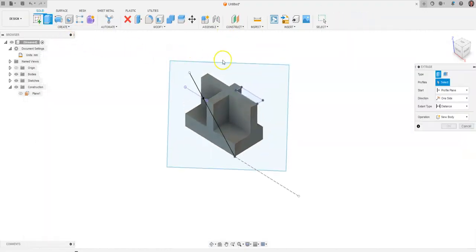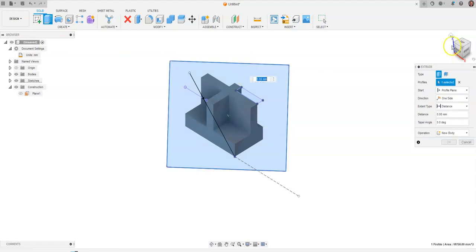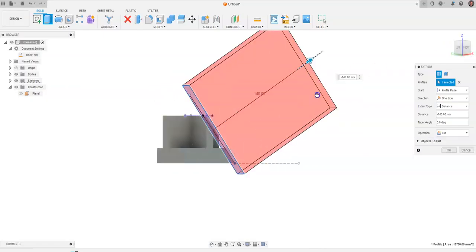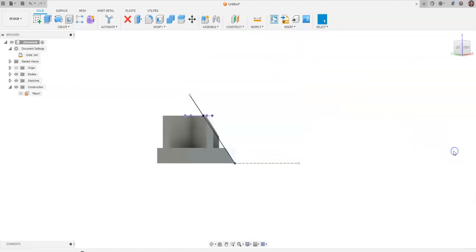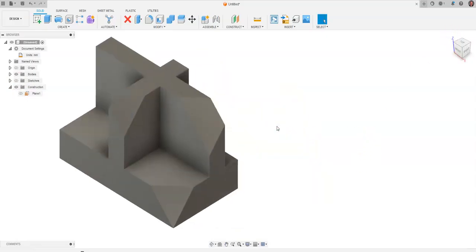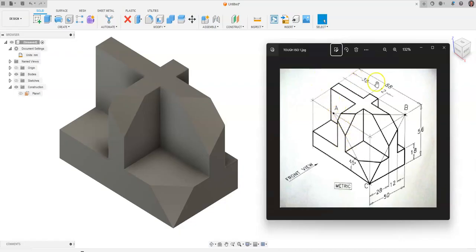We're going to grab Extrude, and I'm going to tap inside of that object, and we can even go to the side here, maybe a little bit of a different view. I'm going to drag straight up off of that, choose Cut, and say OK. Come over to Sketches and turn off the visibility of your sketches. Go to your House button. You just cut off everything. We're just drawing a rectangle and pulling it towards you and cutting off this surface, and this surface.